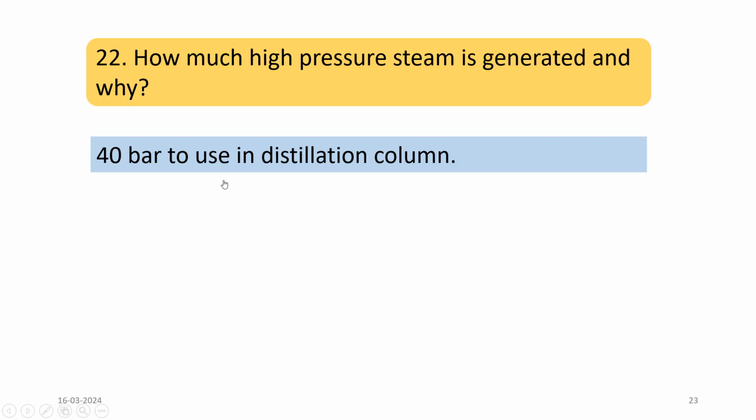Okay, so you have seen in the methanol production chart also that steam needs to be supplied in both the distillation columns and for the compressor. So this high pressure steam is sent there. So this heat of reaction is not wasted. They are converting it to high pressure steam, and this high pressure steam is used in the distillation column.